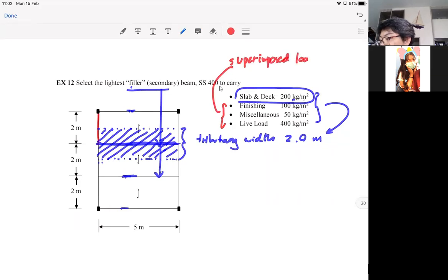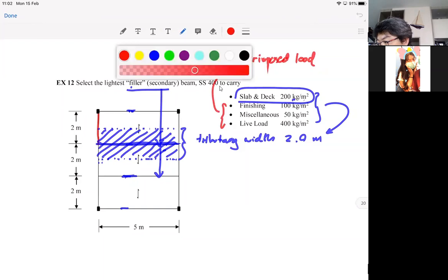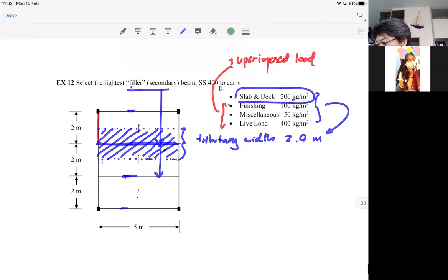Load. You sort of superimpose it on the floor, so that doesn't include the weight of the floor itself. And sometimes you see someone may call this superimposed dead load. Okay, so just know that they're different. And when you do the LFD, for example, you know that you need to use two different factors for these two loads. Okay, but that's my load, and I think